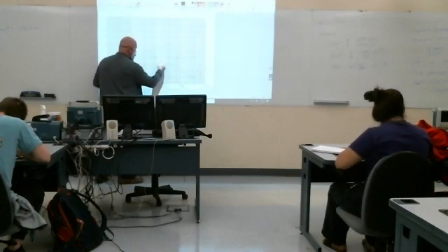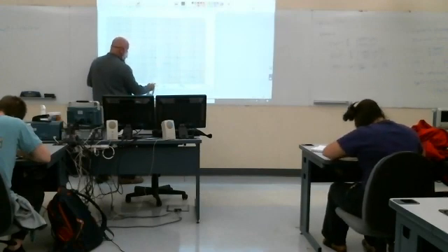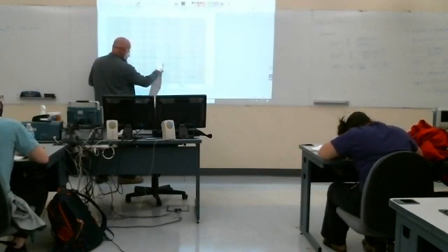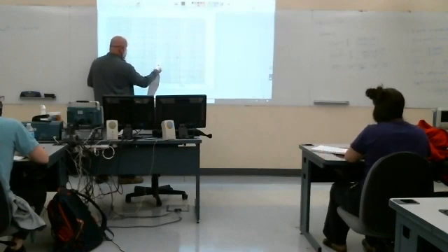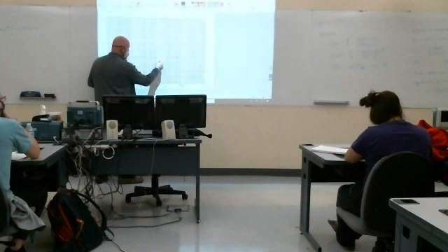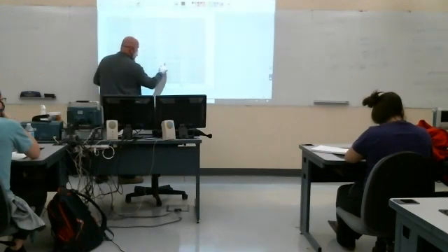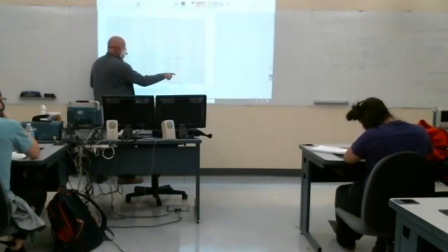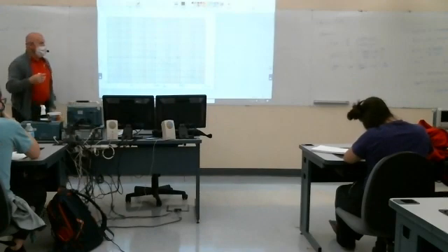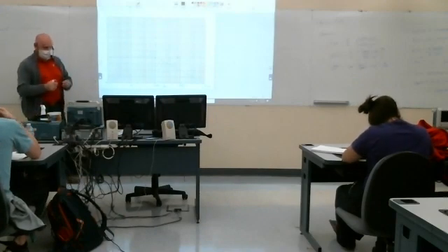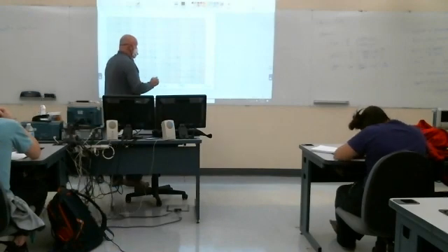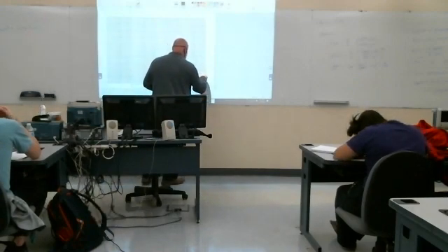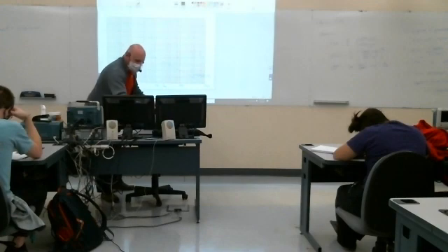That should correspond to a doubling, so 1,000 to 2,000. It looks like I'm slightly off with my line. It should actually go 6 dB, 2, 4, 6. It should actually go right to that point. Okay. And if you lay that out with a straight edge, you should have that. But this is going down at a 20 dB per decade rate, minus 20 dB per decade. Let me see if I can get another color.